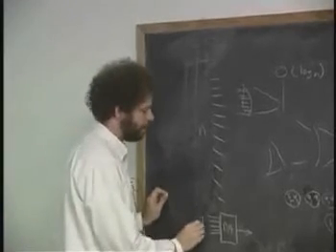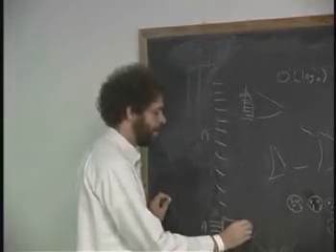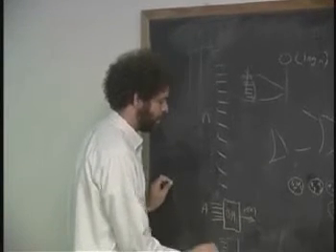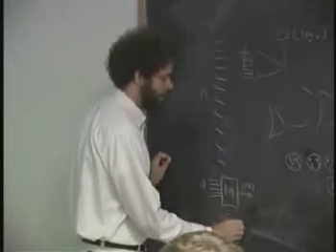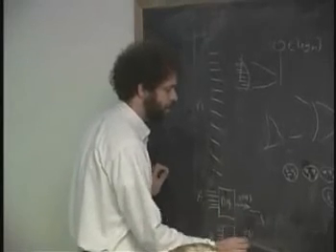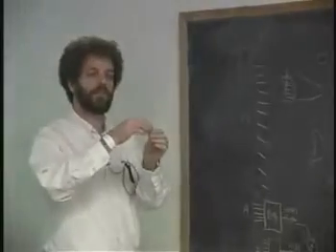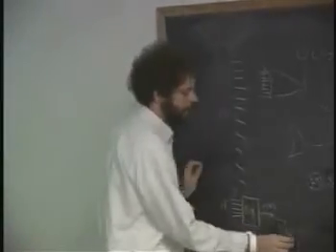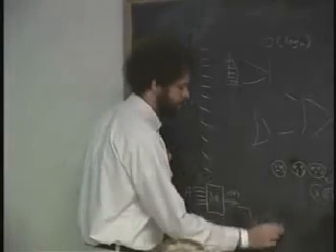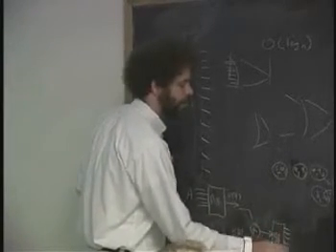So here's A that goes in here, and here's a voltage that corresponds to A. And then I could have another digital to analog converter here that would take B and produce a voltage corresponding to B. Then I could put it into an analog device to sum them, which is similar to putting the 2 pieces of chalk right on top of each other. And then after I got an analog voltage, which was the result, I could put it into an A to D converter, and I could get the sum of A plus B.